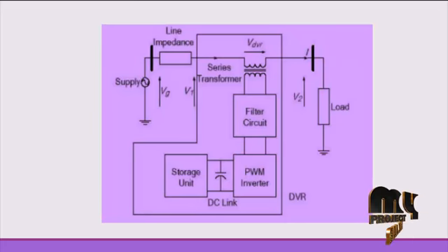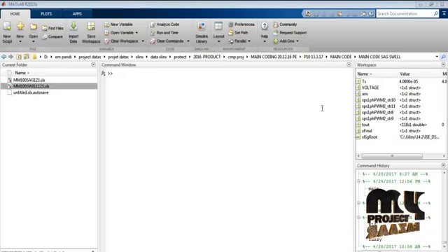such as long duration variations and short duration variations, and other problems are rectified using the DVR method, in between parallel connected shunt active filters and other active filters. That corrects the sags and swells and also restores the original value of the source voltage and feeds it to the load. Next we see the running process of our product.